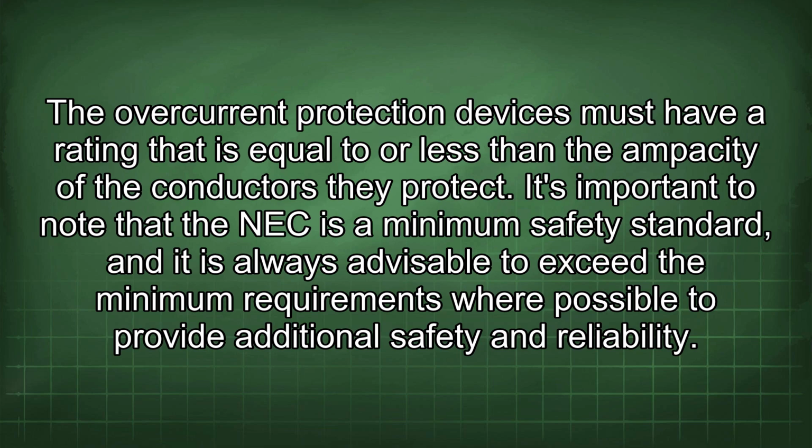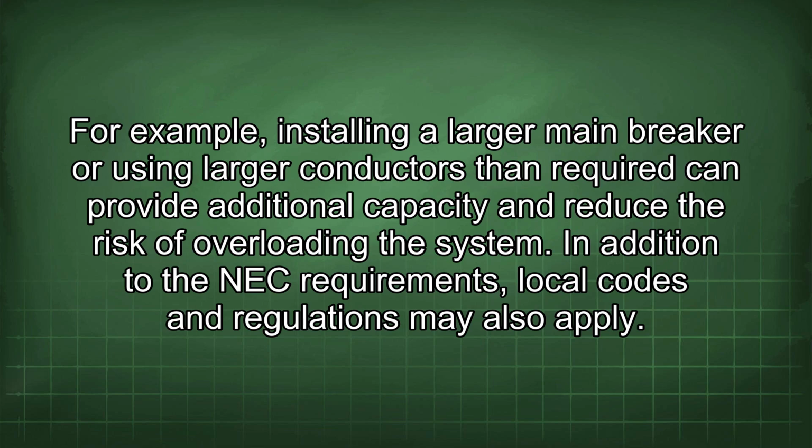It's important to note that the NEC is a minimum safety standard, and it is always advisable to exceed the minimum requirements where possible to provide additional safety and reliability. For example, installing a larger main breaker or using larger conductors than required can provide additional capacity and reduce the risk of overloading the system.